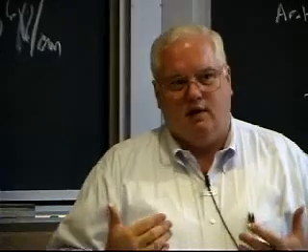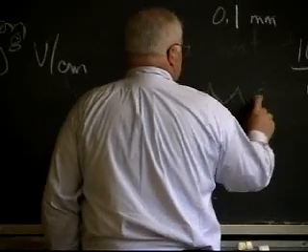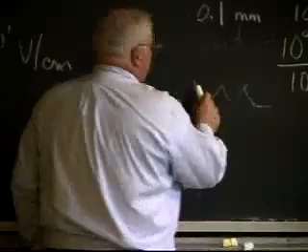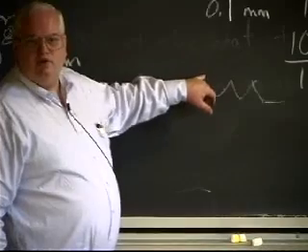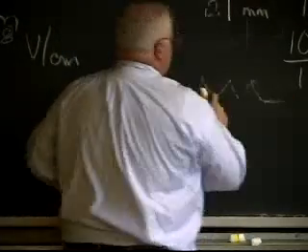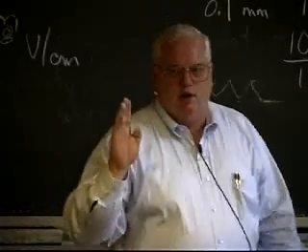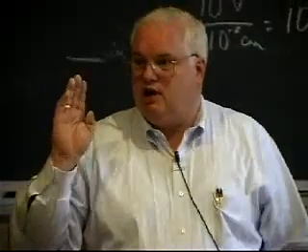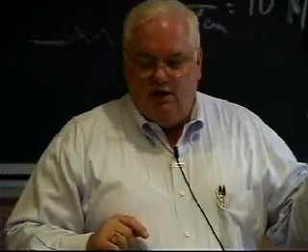Well, you'd say that's not field emission, but aha, it is. It turns out Paschen breakdown in the 1880s was the same as field emission later because I have these little asperities on the surface. And what happens if I have a little asperity on the surface in terms of voltage? I get a concentration of voltage around those points. And if you take something that has a field of 10 to the 6 volts per centimeter, right here at some little asperity on the surface, I can have 10 to the 8th. And I'll get breakdown. I essentially am getting field emission. Paschen breakdown was just an 1880s version of field emission.